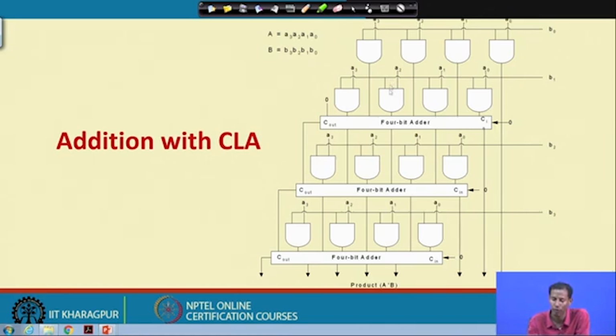So, at the very beginning it is producing this 4 bit sum. Okay. So, apart from the last sum that is directly coming out, the other 3 bits and carry out are again added with B2 A3, B2 A2, B2 A1, B2 A0, and then again it is added here. Then again the carry bit is coming over here, the last sum is coming out from this, and finally I am getting the product something like this.